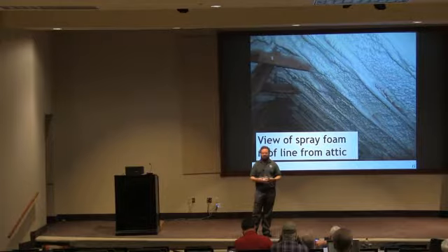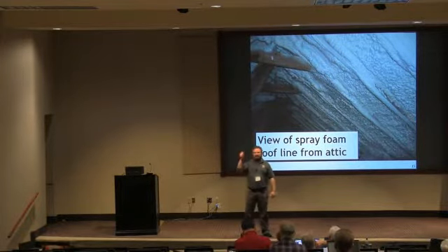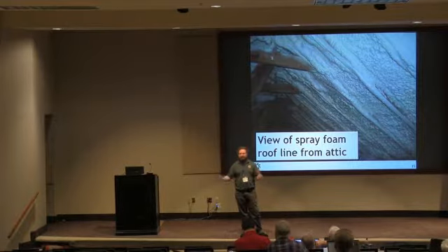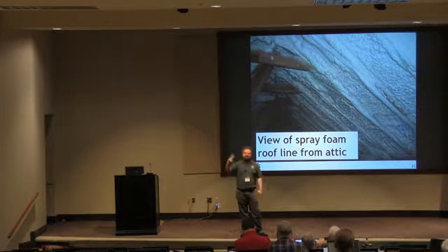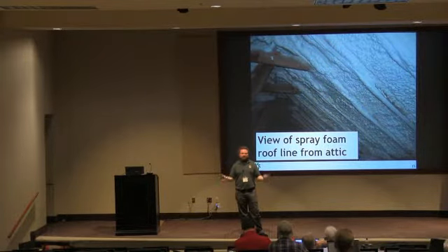If you have a traditional vented attic with HVAC equipment up there and insulation on the ceiling, a radiant barrier retrofit is probably the cheapest, easiest energy efficiency retrofit you're ever going to do. You just staple that up there, and it's going to drop your attic air temperature by 10 or 15 degrees. If you're building a new home with an insulated ceiling, I would absolutely do the pre-manufactured Tech Shield with the radiant barrier on the underside of the roof deck, because it costs a couple bucks more a sheet, and it will really bring down the air temperature in that attic, which reduces the ambient air temperature around the equipment.